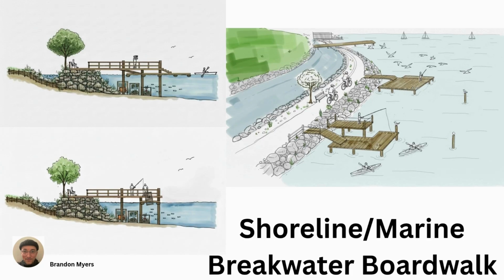For the shoreline design, we developed two primary concepts: boardwalk breakwater system and softscape preservation for marshlands and natural shoreline. The boardwalk breakwater system combines storm surge protection with expanded community space. Constructed as a raised offshore breakwater, the system reduces wave energy and protects against coastal flooding, while serving as a foundation for a public boardwalk.